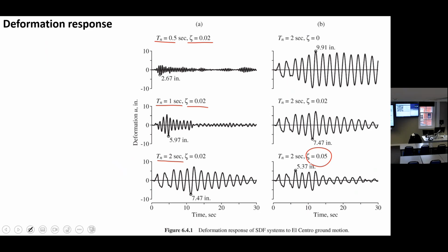If your structure, a very complex one, has a natural period equal to 1 second, I can say this single degree of freedom system, a very simple one, just M and K with Tn equal to 1 second, is for this one. Okay? If you have a very complex structure with a natural period of 1 second, I can tell you your response will be really very close to this one.